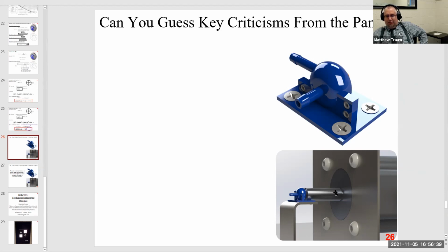So this motor sitting behind it is the smallest DC motor that we could find that would turn at 2300 RPM. So you get a sense of the size scale. And the concern was that this motor would vibrate, and even just a small vibration as it was turning would be enough to completely destroy the seal inside the turbine or inside the pump.